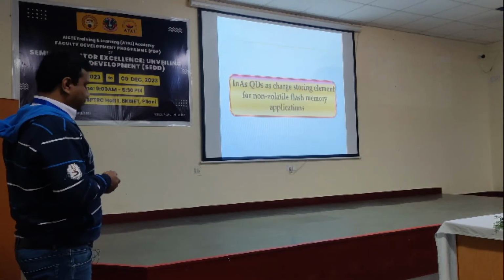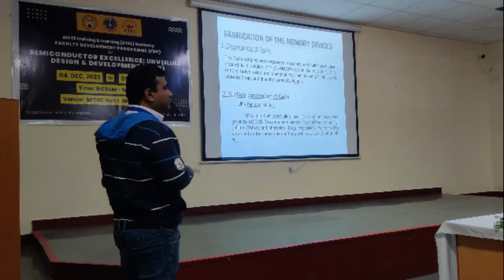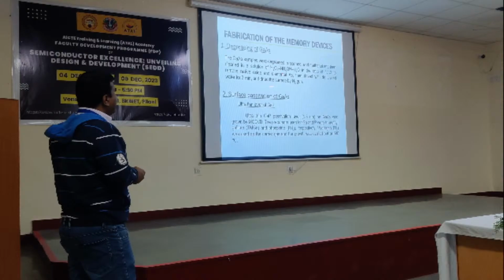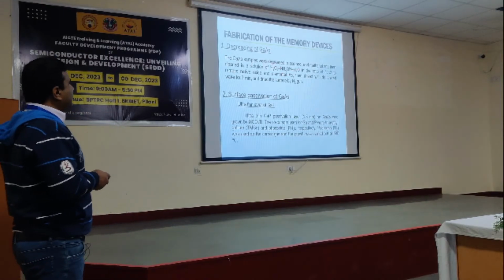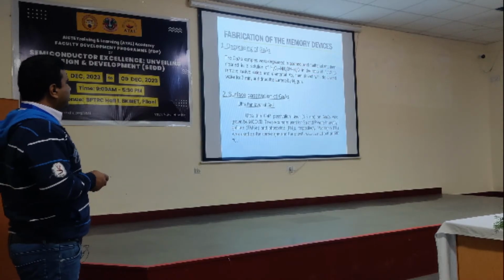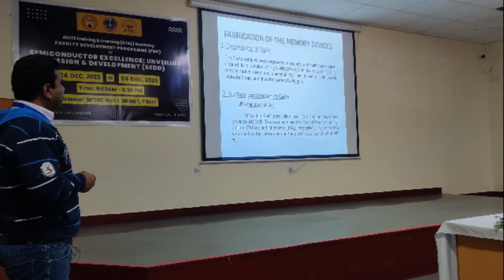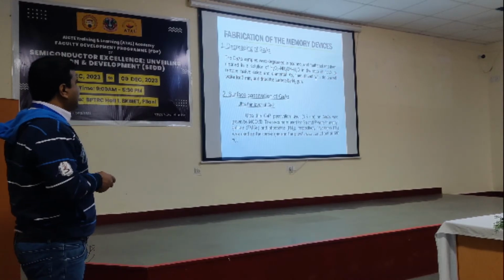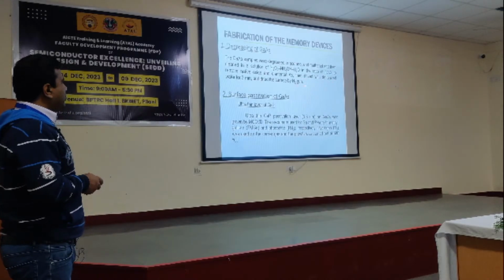Now I am going to the device fabrication part, that is the gallium arsenide MOS. First of all, you have to take this gallium arsenide and clean it. It is degreased by acetone and methanol. These are all related to your device material processing as well. Then there is a base piranha solution, for removal of native oxide and elemental arsenic, then rinse with deionized water. Finally, you dry it with a nitrogen gun.